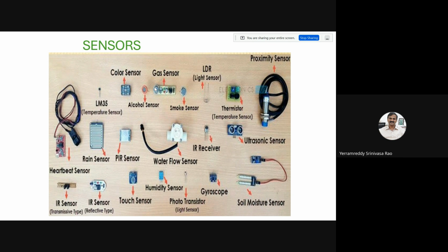Sensor is converting a physical parameter into an electrical signal. Okay, physical parameter. What is a physical parameter? Temperature, pressure, humidity, radiation. These are all physical phenomena, but I want them in terms of a signal. That's why I said go back to physics. I want a signal first, right? Something is naturally changing. Temperature is changing, but I want a signal, 1D signal, 2D signal, 3D signal, whatever. I want it in terms of a signal.